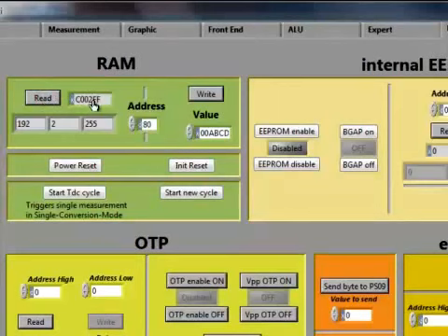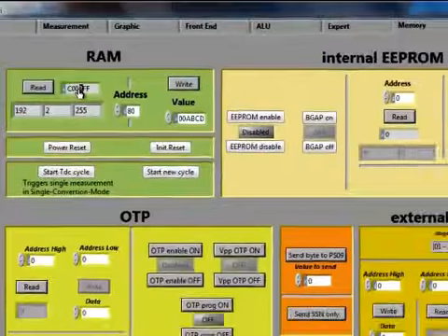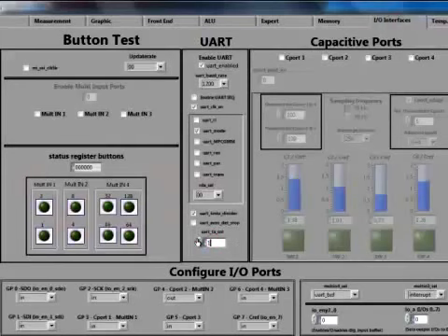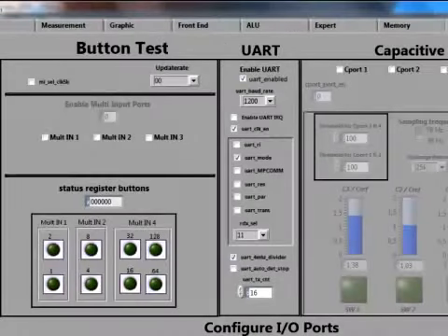Here you can see that bit 9 is set, that is, the transmit interrupt is set, which indicates the completion of transmission. Similarly, you can send up to 16 bytes in one go by setting the byte count here to 16 and then filling the bytes from RAM address 86 onwards.